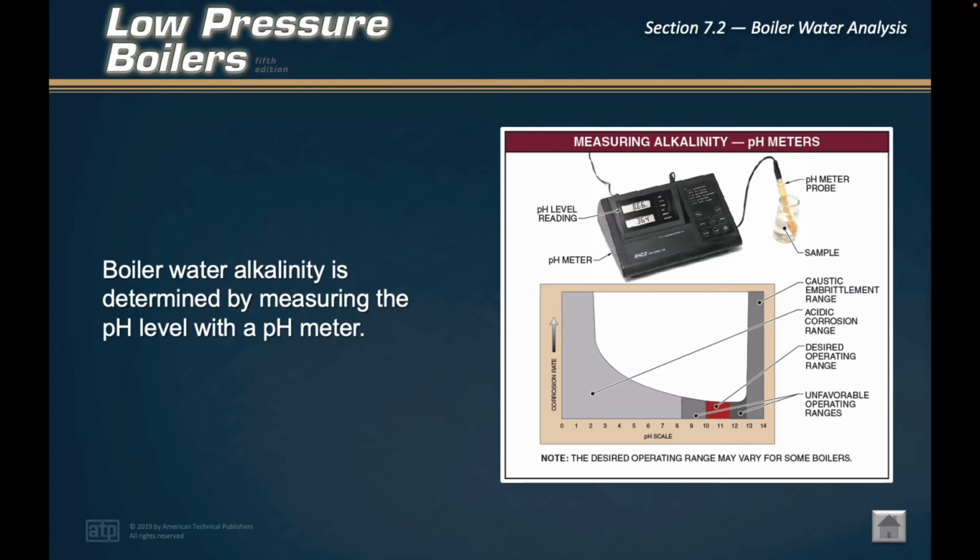Boiler water analysis tests the condition of the water and is used to determine the feed water treatment required. Boiler water is analyzed to determine the frequency of blowdown and the amount of chemicals necessary. It is commonly analyzed for proper alkalinity, hardness, and total dissolved solids.